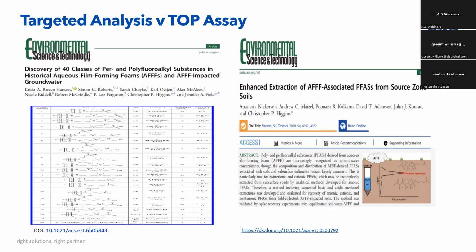But also maybe just be aware that if you're carrying out remediation and you've got benzene impacted groundwater and you're using in situ chemical oxidation, or ISCO, as we call it in Europe, you can actually preferentially transform some of the precursors to the persistent perfluoroalkyl acids.